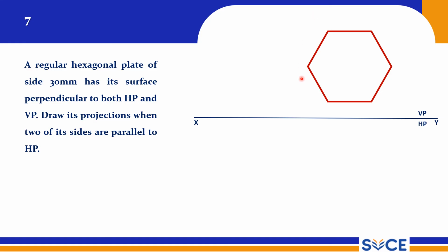So this is obviously the side view. I have drawn it on the right side, so this is the left side view of this plane. Left side view is always observed on the right side, and right side view is always observed on the left side. Please remember this. These are A double dash, B double dash, C double dash, D double dash, E double dash, F double dash. Now this is my auxiliary plane, my picture plane or profile plane on which I get my side view, and for this the reference line becomes this line, and this is my x1 y1. This is how you have to start this problem.